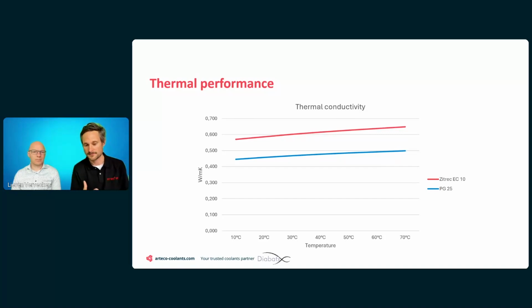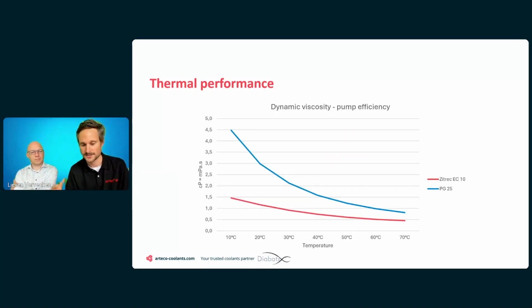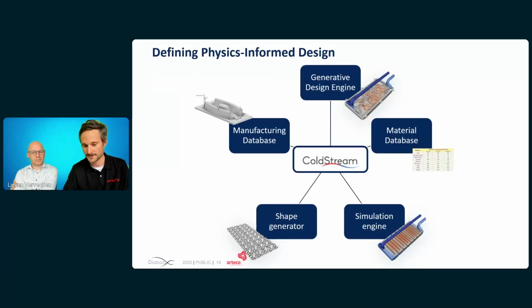We also see a much better thermal conductivity, so the transfer of heat through the fluid. And you can see that the viscosity is much lower, which has a very positive effect on the pumping efficiency. So there you go, that's on the fluid. And there are also a few things to say about the cold plate design.